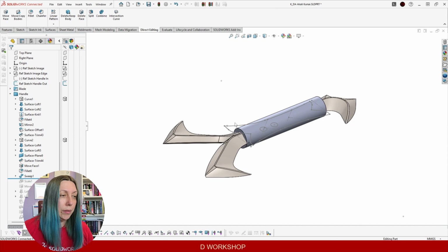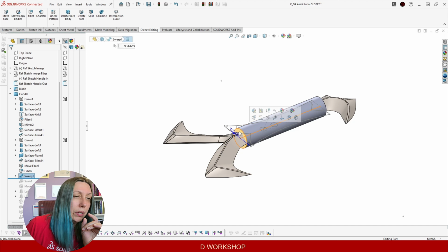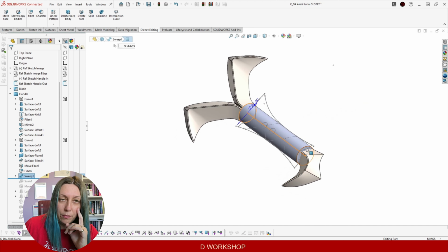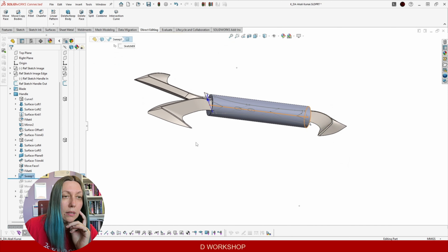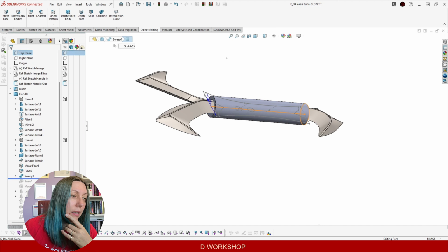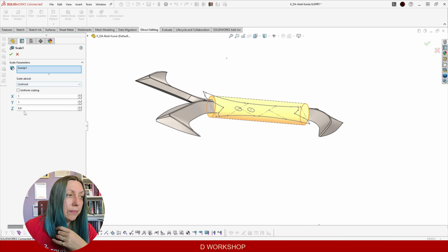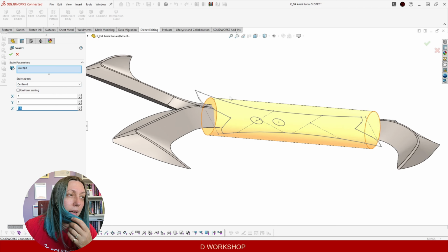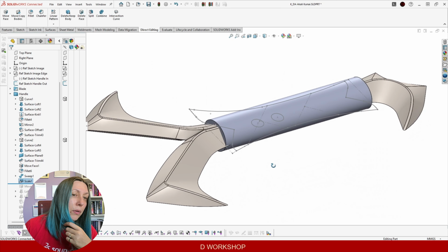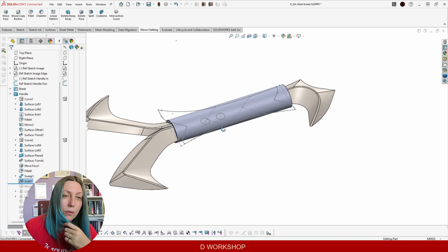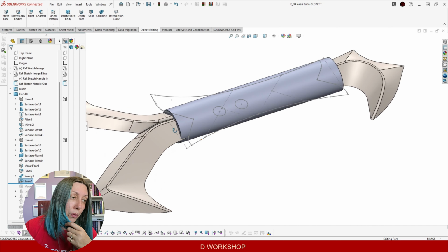It's not circular, but I started like this first because I have both ends of the outer handle without making additional planes, and also because it's elliptic. And to make it elliptic, all I have to do is use scale, but asymmetric, and squish it only on Z, and receive the correct shape of our outer handle, or almost.